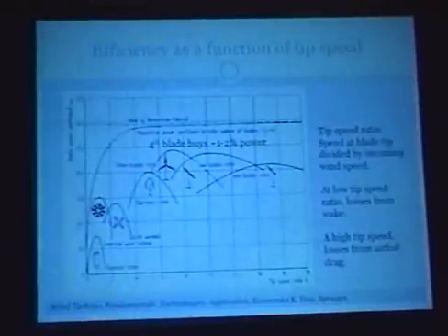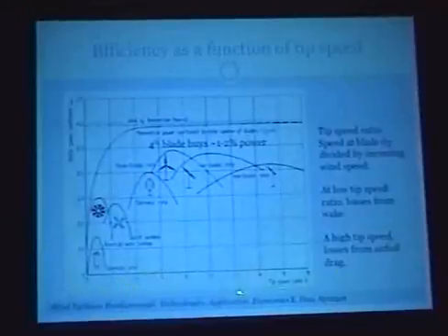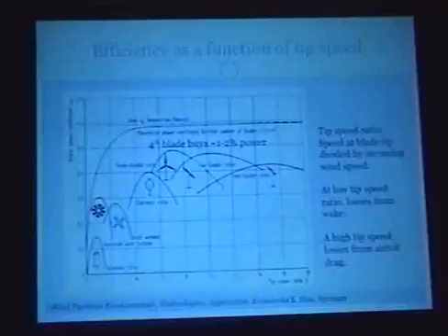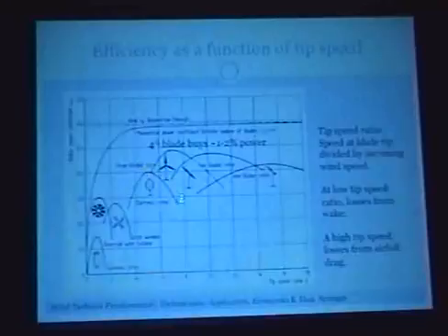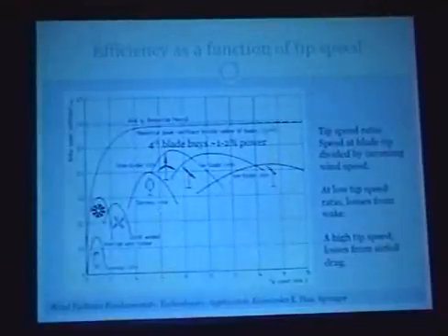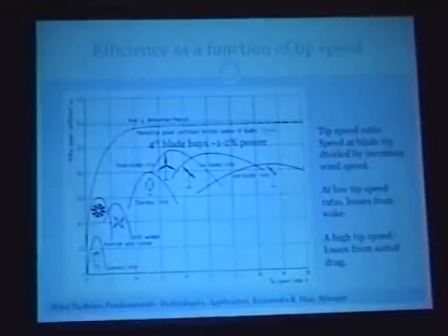do with the wake. And you also know that these real turbines have to drop off on this side as you go to higher tip speed ratios. And the reason for this is what I mentioned in the previous slide, which is that you can have vortices and drag and various terms. And those really start to pick up the faster these things spin. So that's one of the things that can cause the loss on that side. So for each design, there's really an optimum tip speed ratio, and you have to think about that in terms of the power you want to generate and the site.